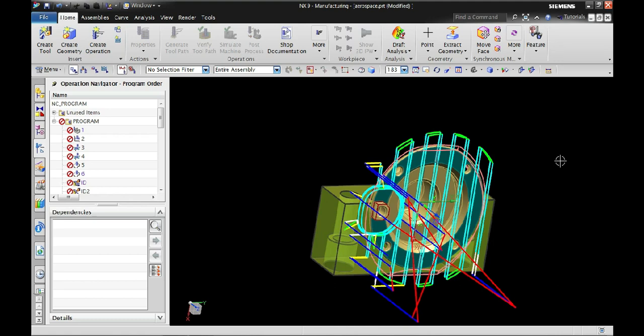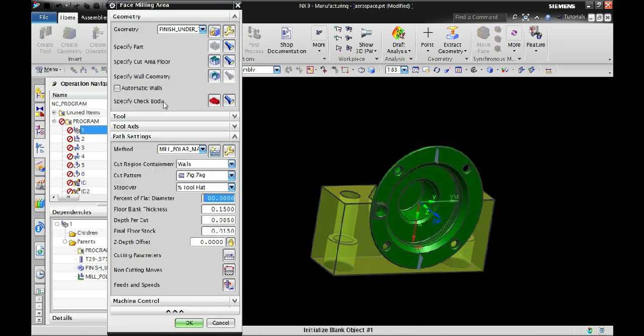So if you use the turning toolpath, if you try to do a facing, you're going to wipe off the peg, the island or the tab that's sticking out, however you call it. So we may end up cleaning it out. So it's good to do milling on this. You can see the milling toolpath. Let's go and see what's done in the milling.